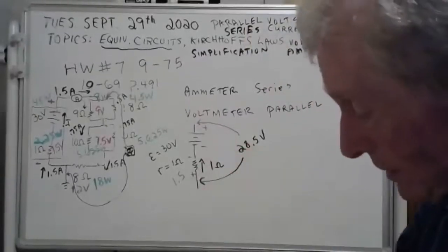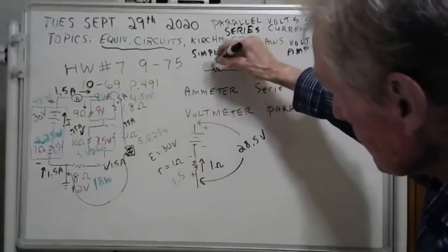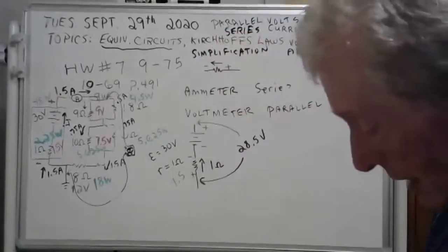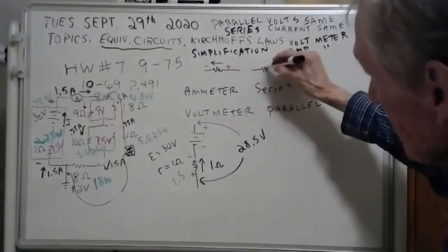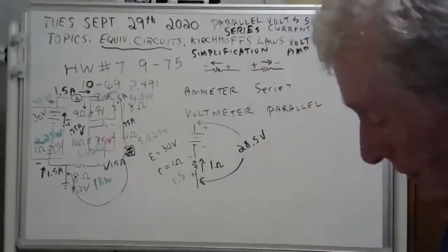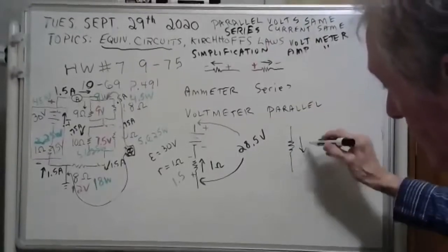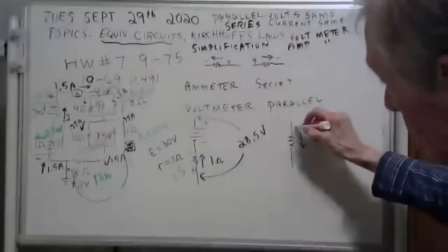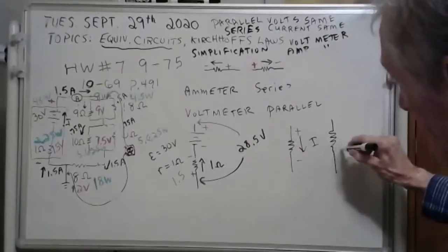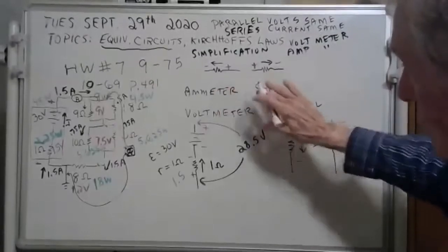And let me repeat about these resistors. Students get confused about this. If you have current going this way, the voltage on this end will be plus, minus, like that. If you have current going this way, the voltage will be plus, minus, like that. Now, if you have a resistor like this, and the current is going down, this is plus, minus. Just memorize this, okay? If the current's going up, this is plus, minus. Just memorize the way that works.